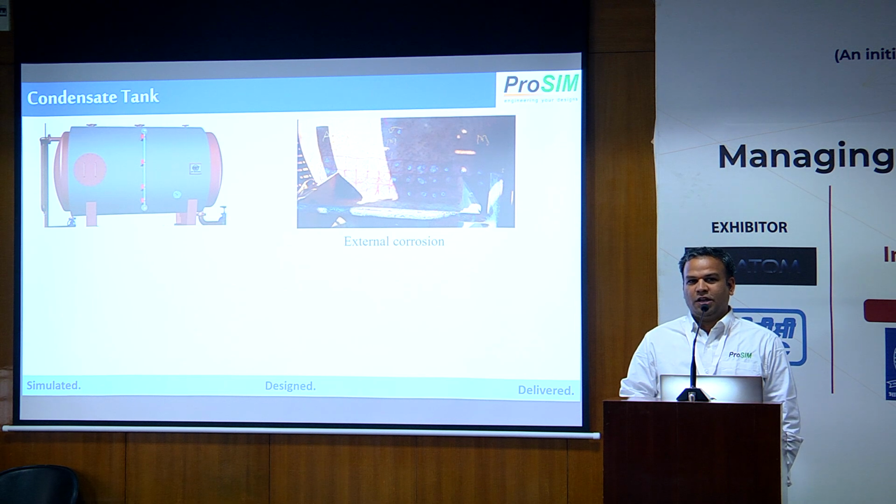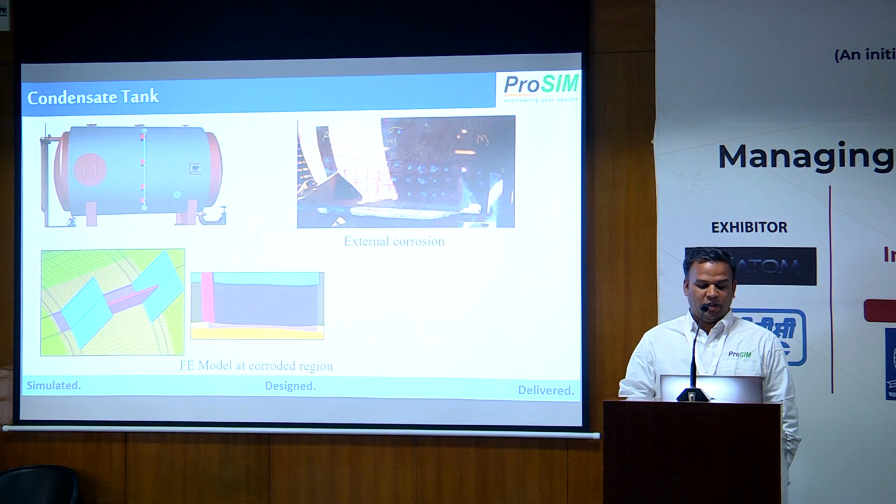Again it is uneven corrosion, but this time it may be checked with elastic plastic analysis, and the question is how to degrade that material, capturing all the properties. We checked the load buckling factor, where we test the stability of the structure, up to what load the structure will hold. So we checked the load proportional factor, the buckling load factor, nonlinear buckling, where we have to tell what the effect or what the thickness could be over there.